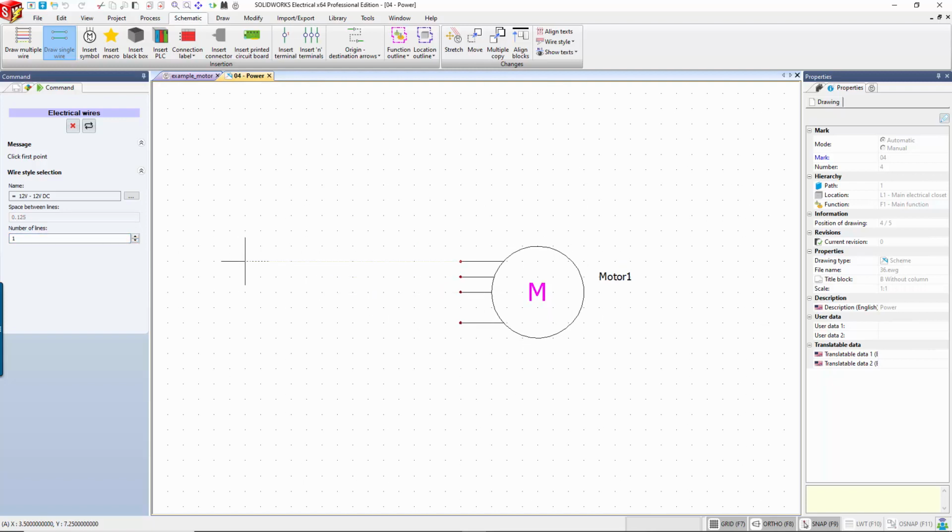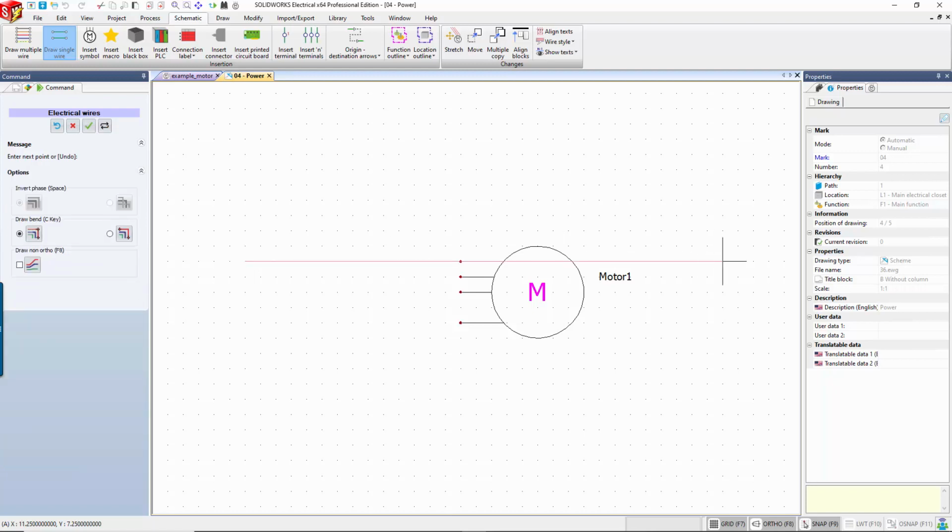And what I'll do is I will left click and draw a wire. And a lot of the time I will overshoot the wire to make sure that when I complete the wire command, the trimming function is working. One, I'm making sure of that because I am too lazy to trim my own wires. And two, if the wires don't trim, and I think they should, that also means the database doesn't think those wires are connecting.